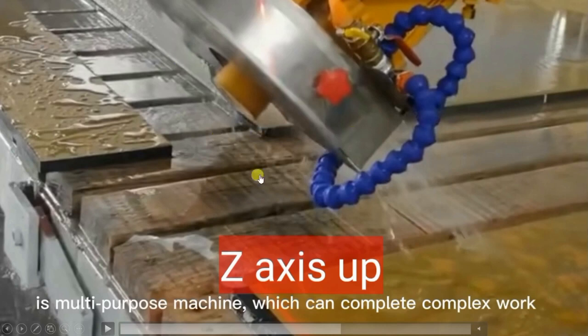Now there is a question. Here there is no any sensor to determine that it has completed its shapes. So how it is operating? So every servo motor has an encoder within itself. So the motor and encoders are on the same assembly. So through the encoders, drives get the feedback that it has traveled the required distance. So what in the PLC logic we will write, store the pulses coming from encoder.